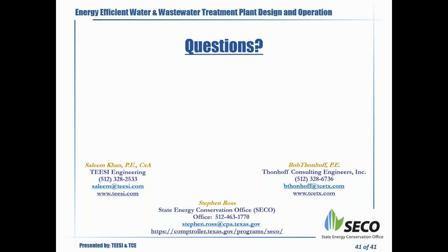Let me see if any other questions popped up. Okay, this is Bob Tonhoff again. We had one comment regarding the ultraviolet disinfection costs of the 7-year payback. It was a comment regarding whether to use the low pressure bulbs versus the high pressure bulbs. And the comment was essentially buyer beware of the high pressure, because they use a lot more electrical power than the low pressure.